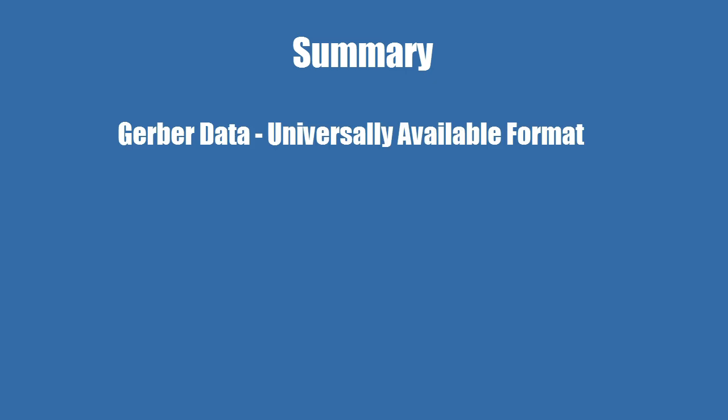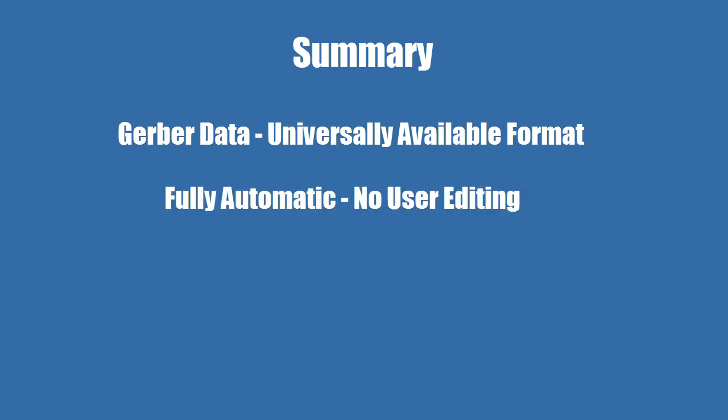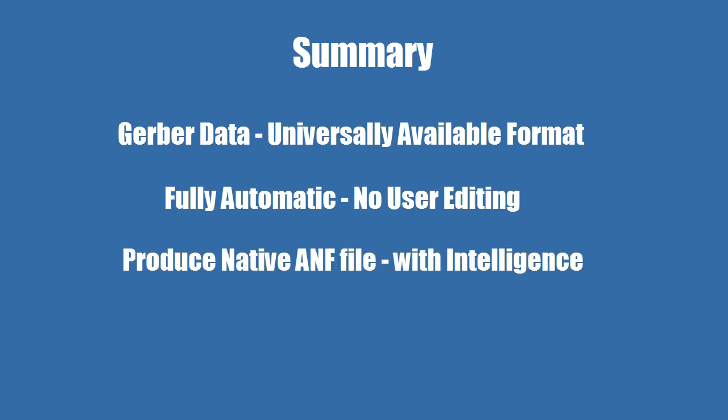To summarize, by using Gerber data, we make our solution independent of whatever layout tool you choose to use. Second of all, NETEX-G runs fully automatic, and there's no need for user intervention or expertise other than to load the data in the right order. And finally, we produce an ANF file, which is native to the Ansys and Ansoft environment. It includes the stack-up, the layers, the vias, and net information in pad stacks. So we think it's a very good solution for what TriQuint is trying to do.